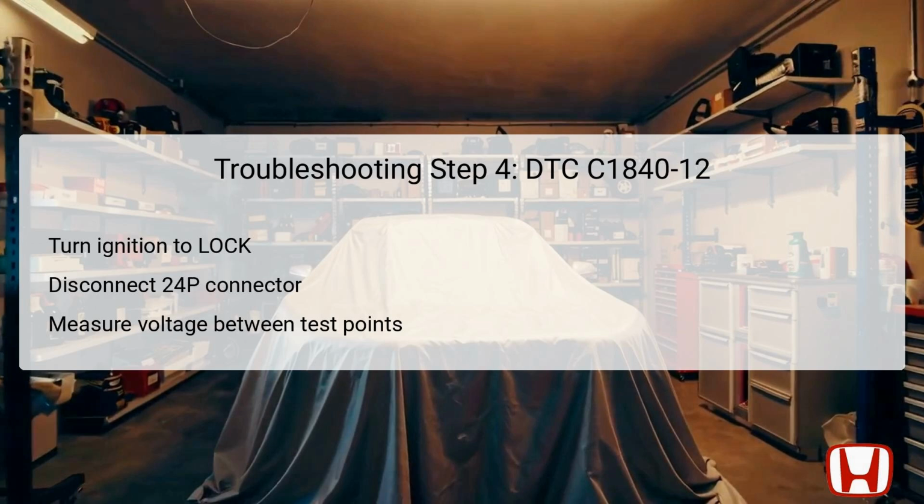Continuing on to troubleshooting step 4, begin again by turning the ignition switch to the lock position for safety. Disconnect the real-time AWD control unit 24P connector prior to any measurement activities. After the connector is detached, turn the ignition switch back to the on position. With the 3P connector from the rear differential fluid pressure sensor still disconnected, measure the voltage between the two designated test points. This measurement is crucial for assessing the condition of the PS1 line.